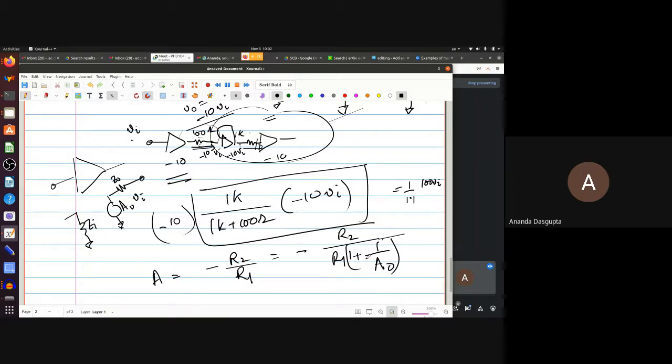The previous one had a resistance added to an inverse gain, and resistance, of course, is dimensional. The inverse gain isn't. So that's an illegitimate statement. But maybe it's something like this. I'm not sure it is exactly this. Doesn't matter. This captures the right idea. The point is the circuit components are imprecise, and A0 will be pretty fickle. It can go from 10,000 to even 100,000.